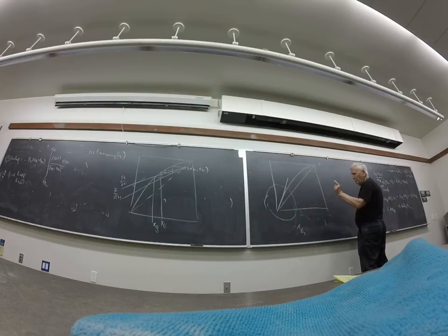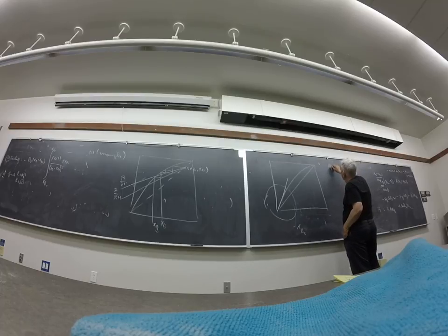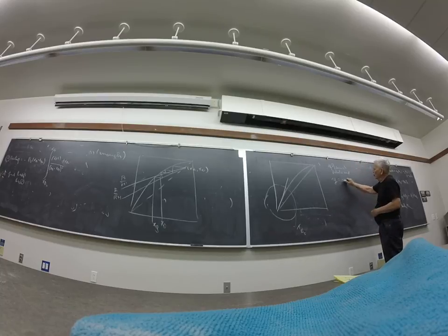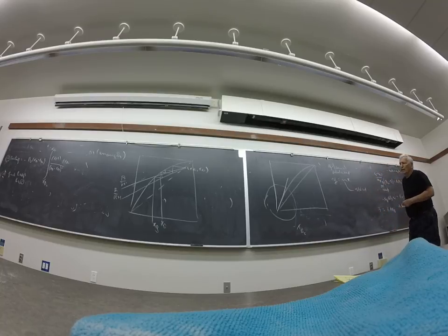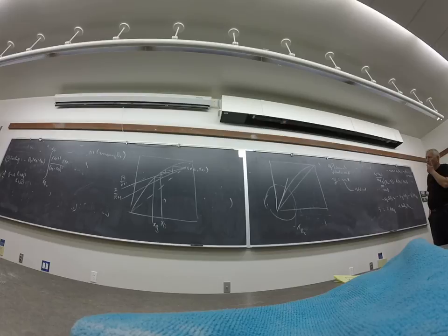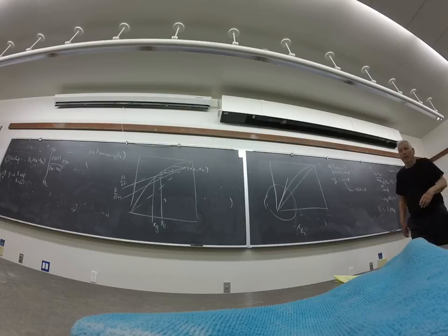So if my problem is at the dilute end, I might just write y equals mx. m is the slope of the equilibrium line at the bottom. So m is really alpha at x equal to 0. Now, I can probably get away with no graphical work. So we might see how this goes.